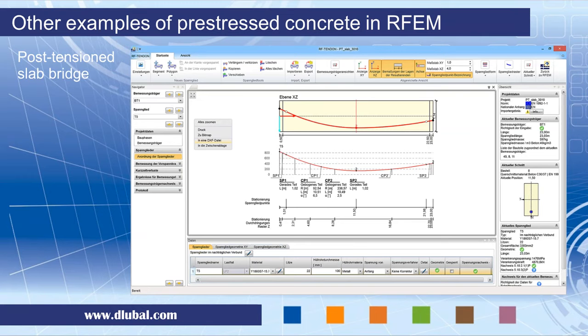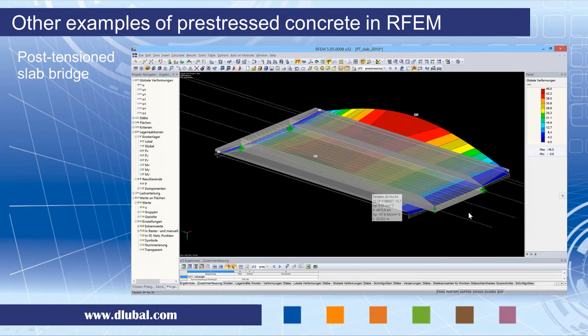Of course, in each of these result beams we defined such tendons. I defined it exactly according to that textbook, and then we can get the results back in RFEM. This is the effect of pre-stressing and the upward deflection, in this view from the bottom of the bridge.